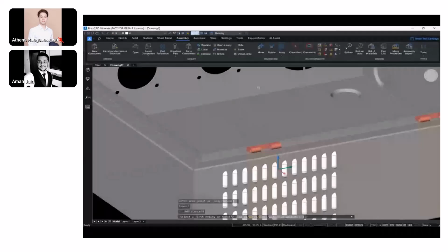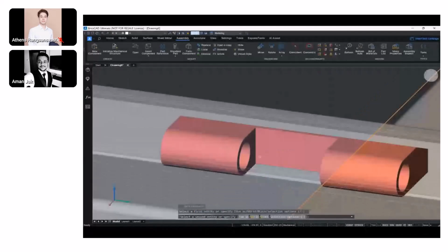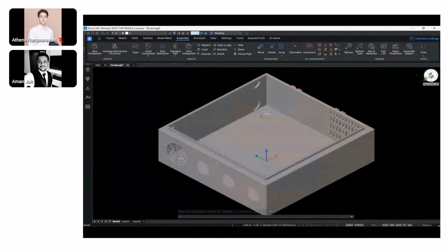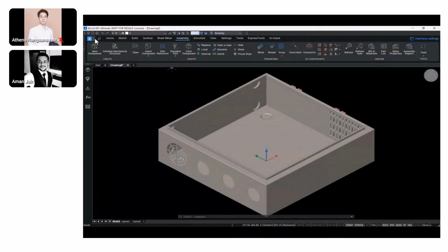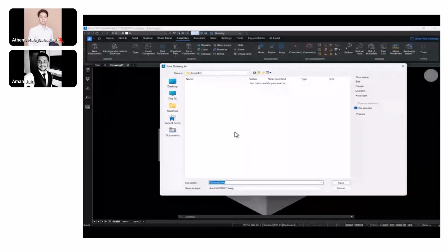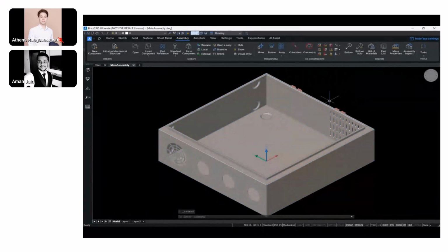The gizmo, or the manipulator, helps us determine which degrees of freedom are free and which are the ones that are locked. So essentially, if it rotates in one particular axis or translates in one particular axis, then we know that these are the degrees of freedom that are free for that particular component, right? So that is how we can check the free degrees of freedom, and if needed, they can be constrained at a later stage using the constraints.